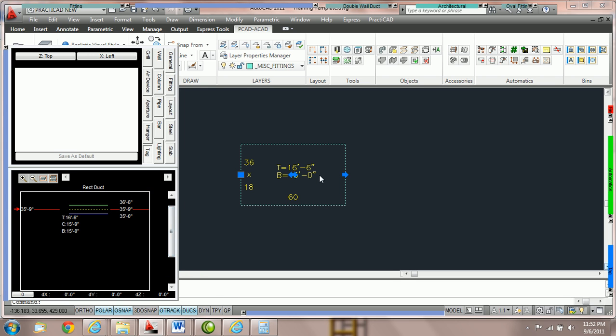Same thing with the top. So the tag is actually showing us the distance between the bottom duct and our relative bottom point, or our relative 0 point. Whether or not this is actually set at relative bottom doesn't make a difference. The tag is actually targeting the 0 relative mark. In other words, even if this is set so it's not relative bottom, here you can see it's targeting this mark. This tag takes the absolute elevation and subtracts the relative 0 mark.